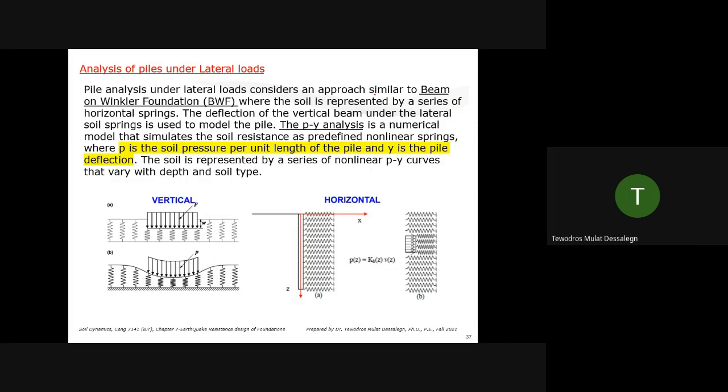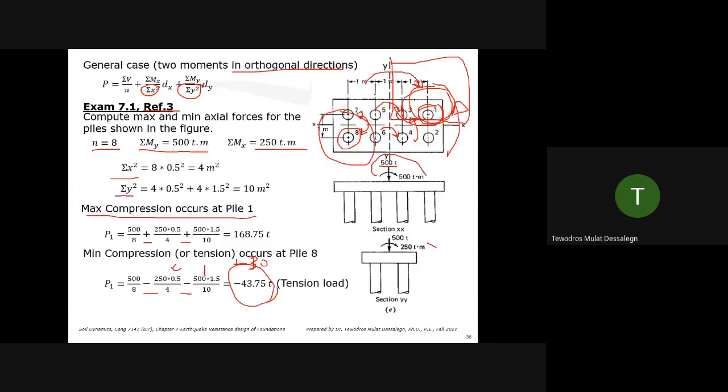Analysis of pile under lateral loads. Now, that's the previous section. This section is only for moments and vertical force. But seismic also will give you what? You will have lateral loads. And usually we don't design this connection to be fixed. There will be a very large moment which will cause cracks. So there will be some flexibility for some ductility. If this is too huge, we may use batter piles to take out lateral forces.